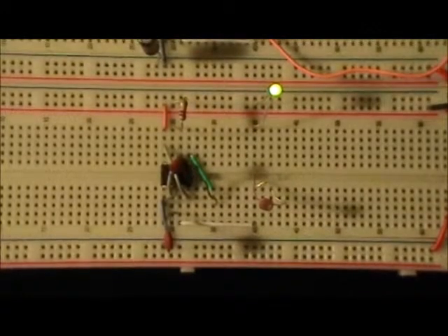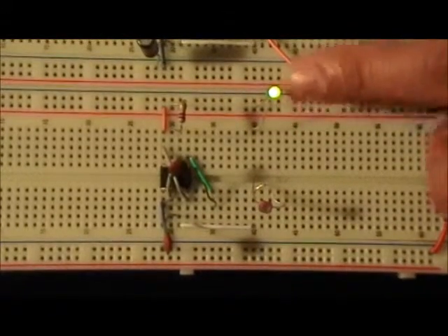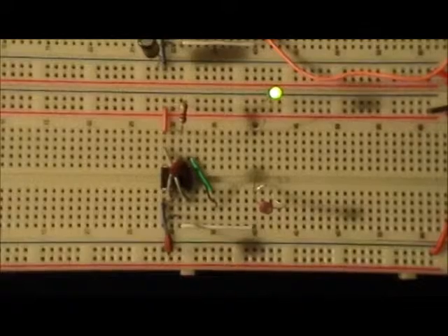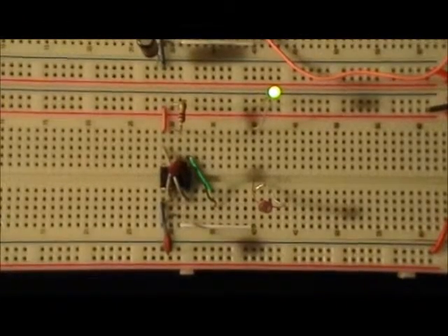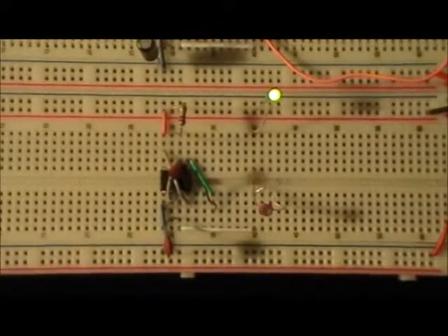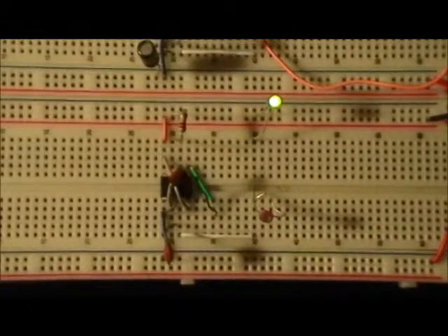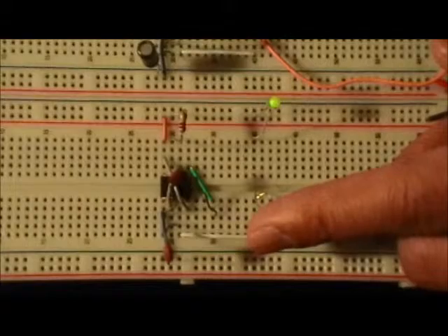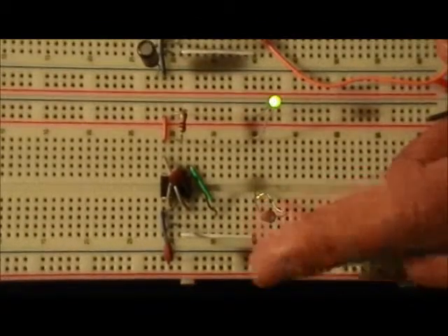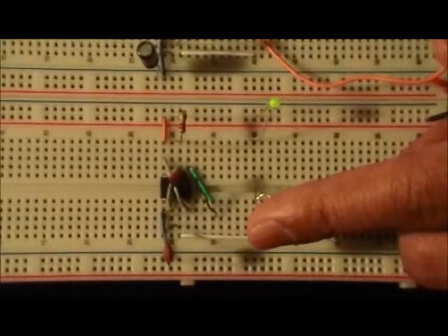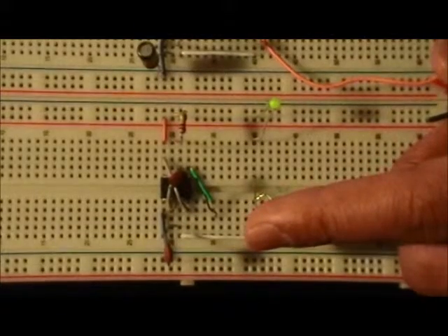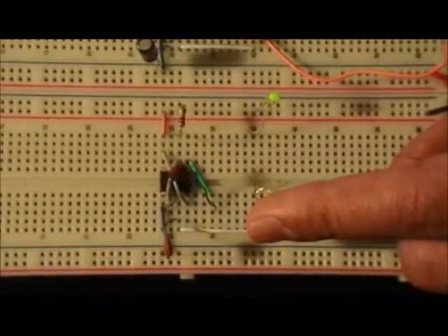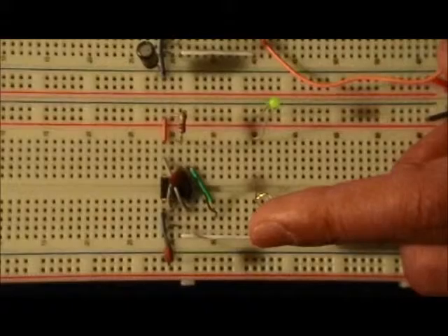Alright, so let's put our battery in. If you notice, this is the LDR at its normal brightness. We're not blocking any light, but we're not adding too much light either. So now I'm going to put my finger on the LDR, and let's see what happens to the LED. It's decreasing every time I put my finger on it, blocking off light, meaning there isn't enough light to give enough energy to the electrons to jump onto the conduction band.